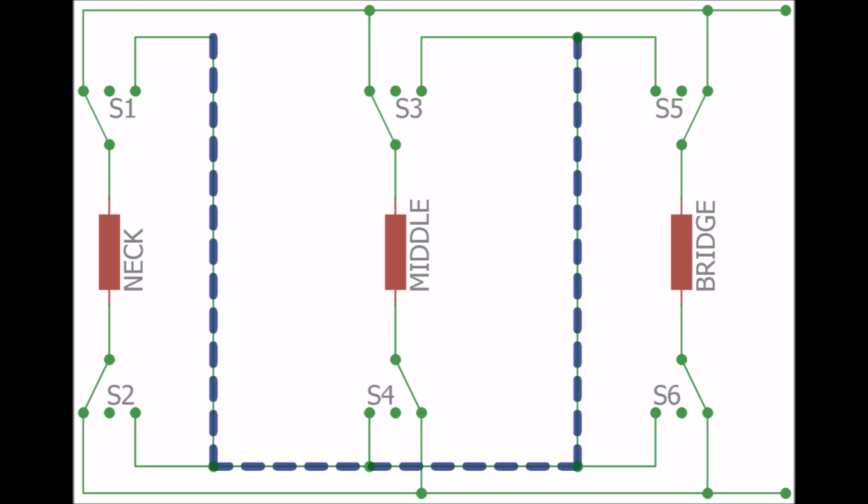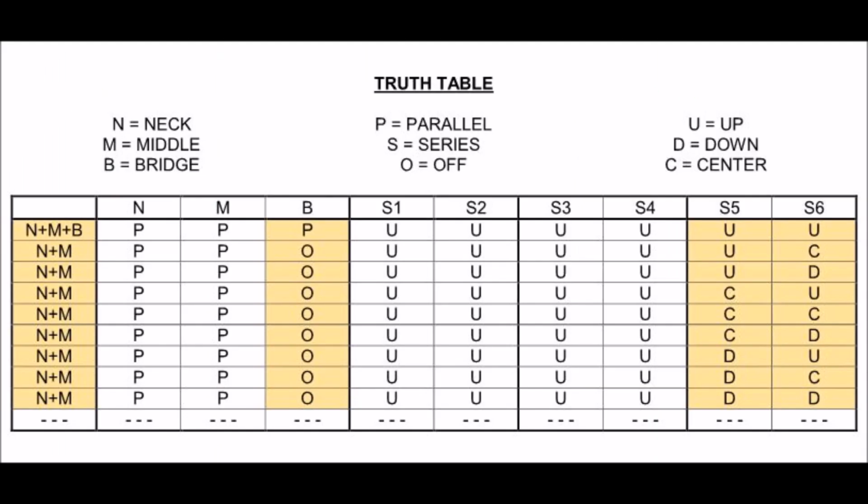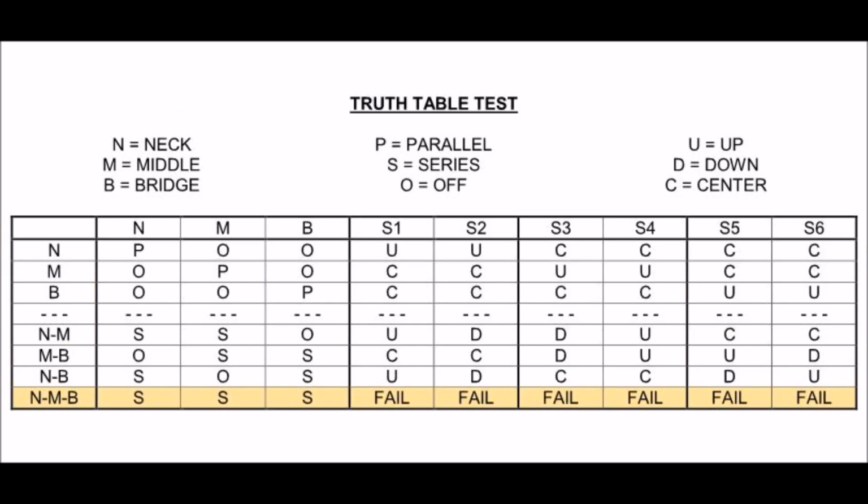Eventually, a rudimentary circuit diagram is produced, which will be our base circuit. Observe that the series connections, and the parallel to series connections, share a common internal bus. To test the logic operations of the base circuit, permutations of all the switches are traced and tabulated in a truth table. To abbreviate this procedure, we only need to trace the connections that are of interest, that is, the 17 parallel, series, and compound connection combinations.